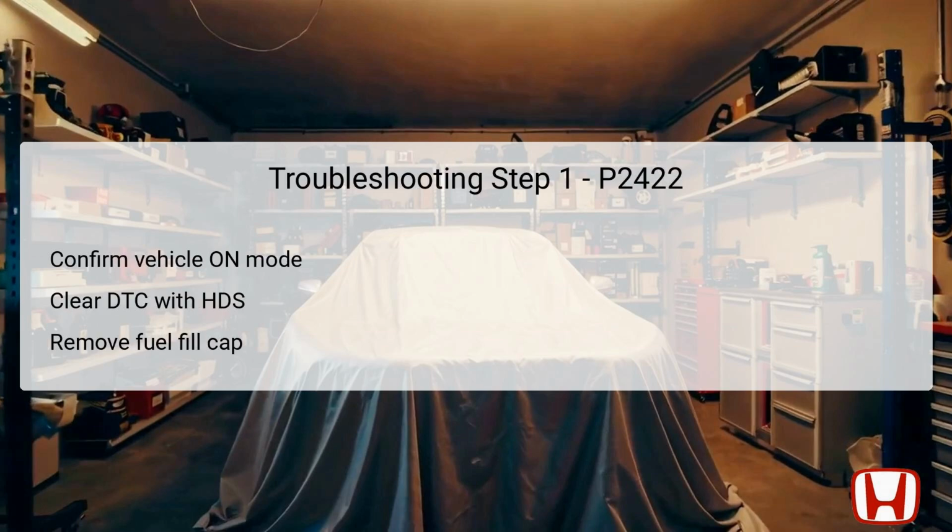The first step in troubleshooting DTC P2422 is to ensure that the vehicle is in the on mode without starting the engine. This allows the Honda Diagnostic System, HDS, to communicate effectively with the vehicle's onboard computer systems. Next, you will need to clear the DTC using the HDS. This process resets the vehicle's diagnostic memory, allowing you to retest the systems.